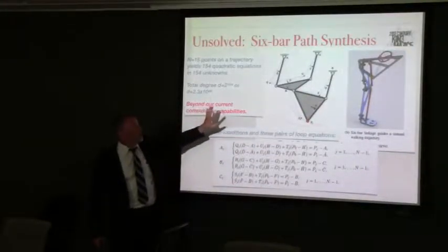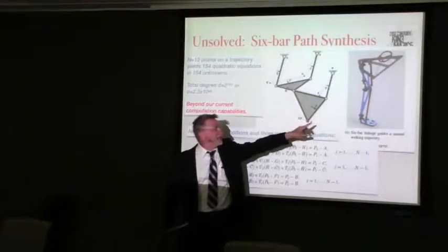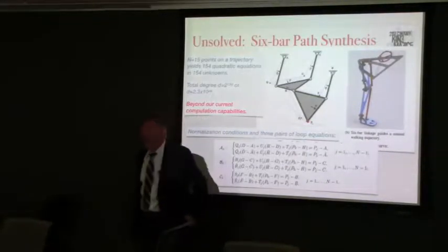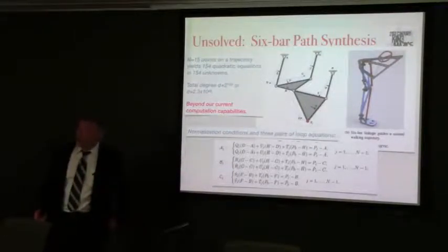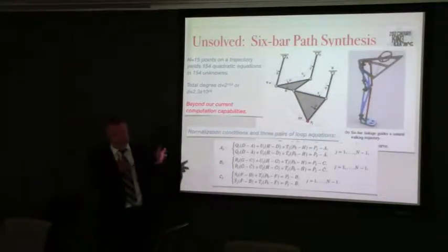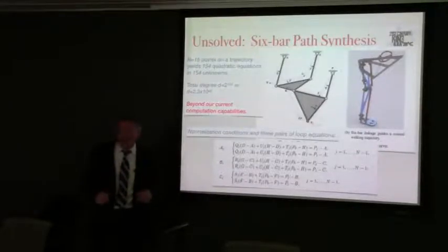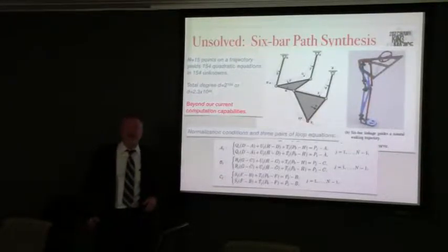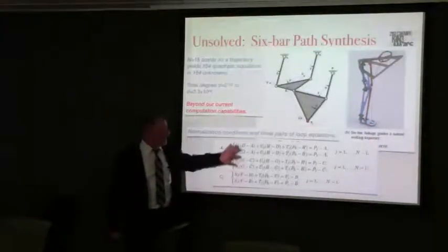But in order to solve the path synthesis problem, and we were working on this problem because we wanted to develop a leg brace that would track natural walking movement, we would take the motion capture of how a person walked, and then we tried to design the brace so that it would match that motion. It winds up that you have to solve this set of loop equations.